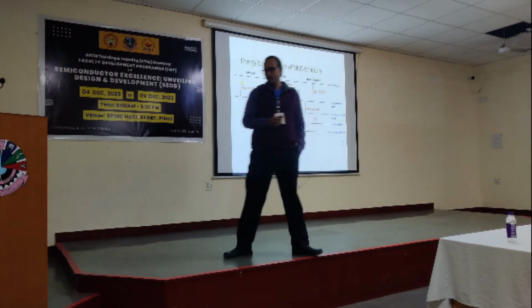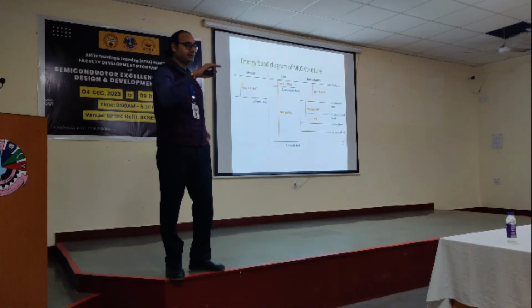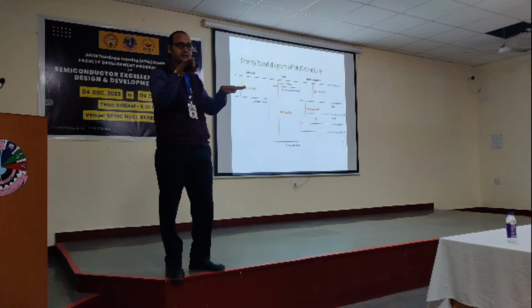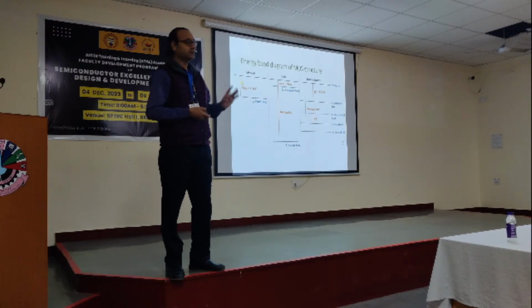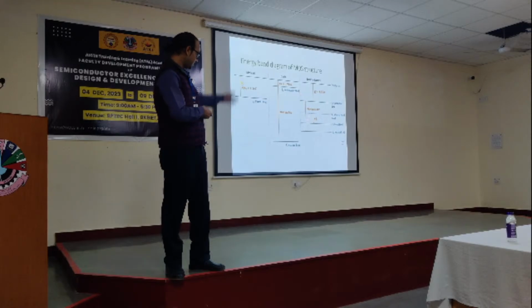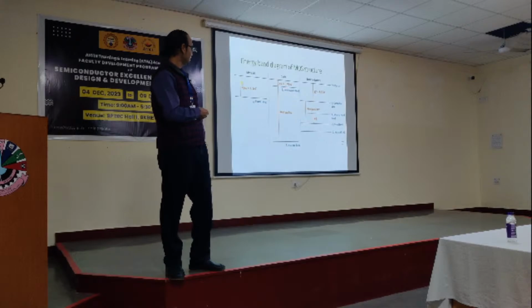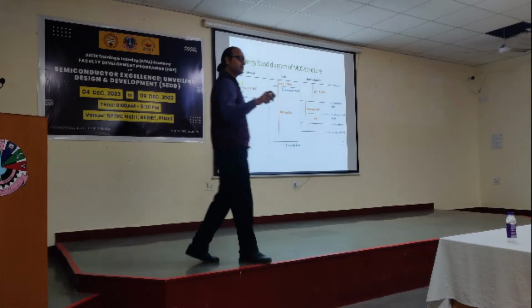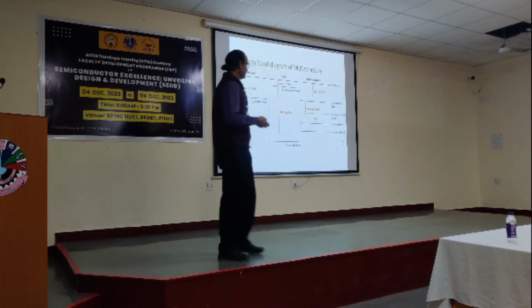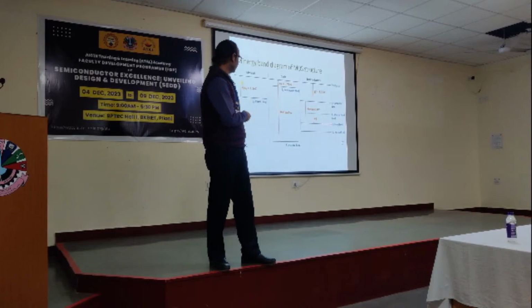Right? Whenever there is band bending, that means there is electric field. If no bands are bending, that means electric field is zero. That is another point. So here, under this situation, electric field is zero in the semiconductor or in this oxide. Band bending means electric field. And one more rule: current flows means Fermi level will not be the same.